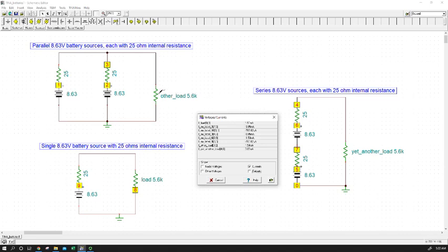But for now, we let the simulator do that. In fact, that is what the simulator actually does. And we can see that if we use two sources, we actually do in fact get the theoretical current through the load. So that's an example. It's not very dramatic because 1.54, 1.53, not too different. But you're beginning to see now the benefit of the current delivery capabilities of a parallel configuration.